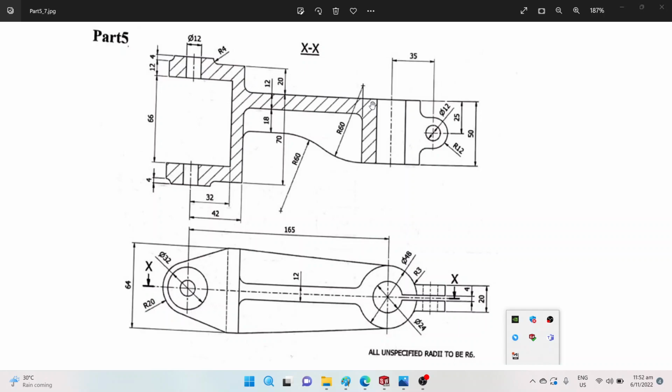I'll sketch on my top plane and I'll extrude down to create this part. For another plane, my top plane will be on this flat edge, on this flat plane, and my x and y will be from this circle. So I'll put the center of the circle as my x and y. Now when I approach this problem, how I would like to do it is that I will draw the component on the left side first, followed by the right side. Okay, and then last, I will go on to do the rib.